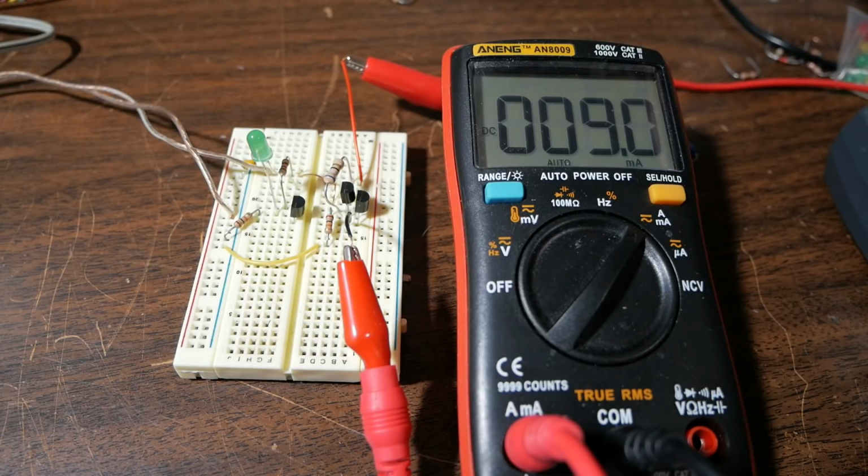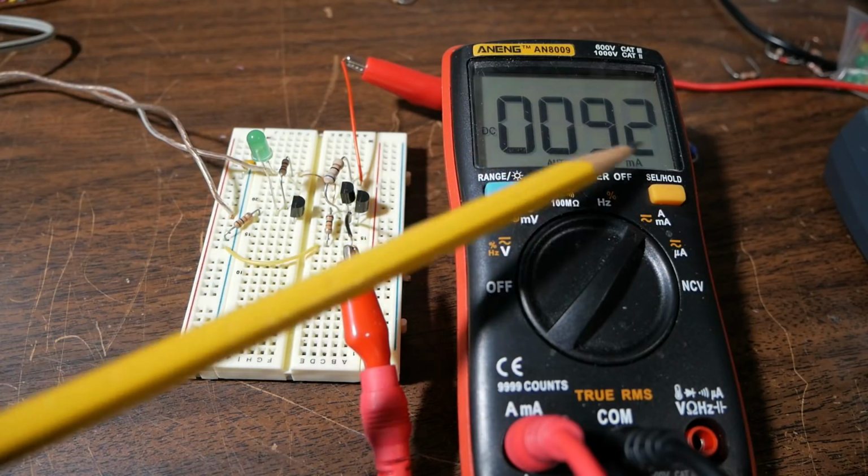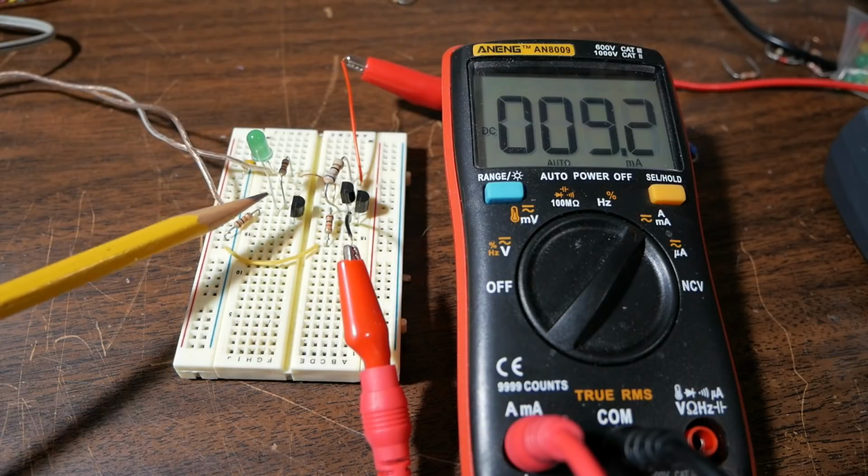We're at 1 volt. It seems to be still in regulation here. Okay, I think we're dropping out. Yep. That's 0.7 volts, 0.8. It's picking back up. 0.9. Looks like 0.9 volts. That's the dropout voltage. So I'll bring this back up. And it stays in regulation. So it doesn't vary near as much as the other circuit did.